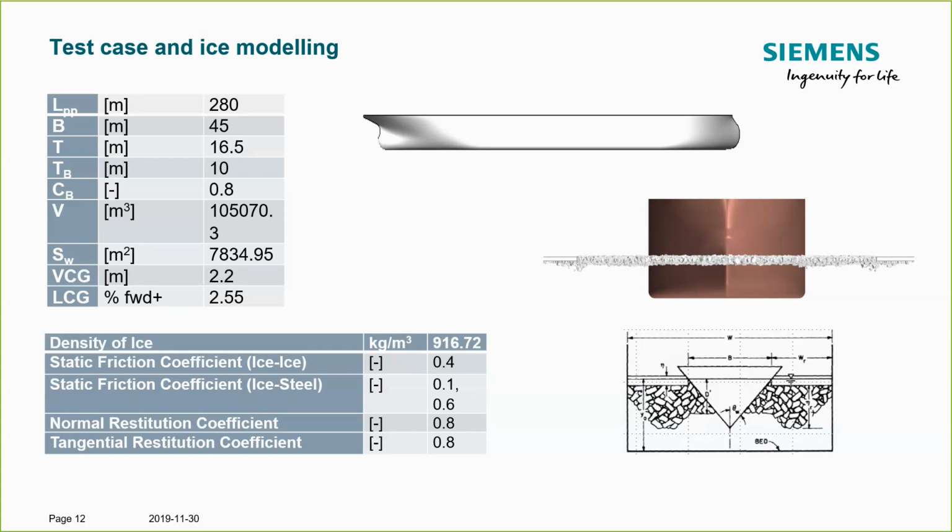And on the very bottom of the series of schematics here, you can see a schematic from the textbook of how brash ice is defined. Usually, if you have the intact ice sheets to the port side and starboard side, you can see these characteristic humps to the negative vertical side that form if the brash ice is formed. And you can see here, upon initializing the ice flow in Star-CCM+, that this situation can very well be resembled.